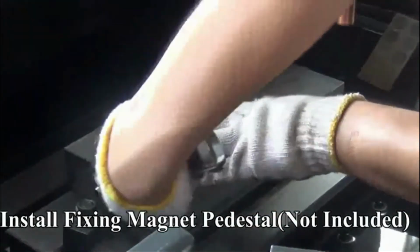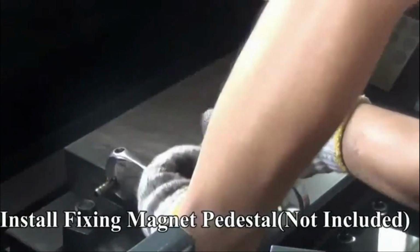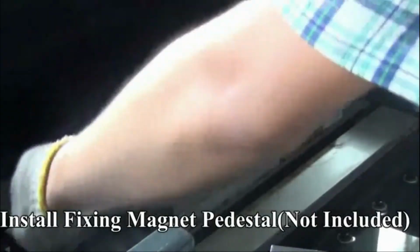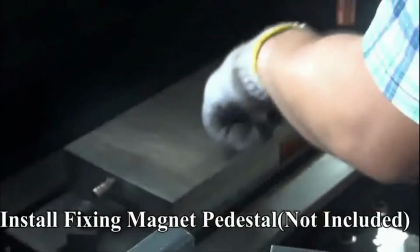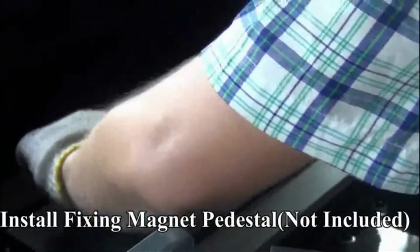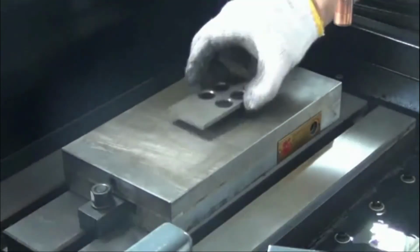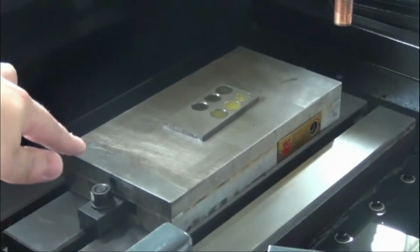Before starting the machining, we want to mount the workpiece very rigidly and firmly on the table. Then afterwards we can easily and precisely carry out the machining on that component. For that purpose, install and fix the magnet pedestal on the table surface of the EDM machine. Next, once we have fixed that magnet, we can directly hold the workpiece on the magnet surface